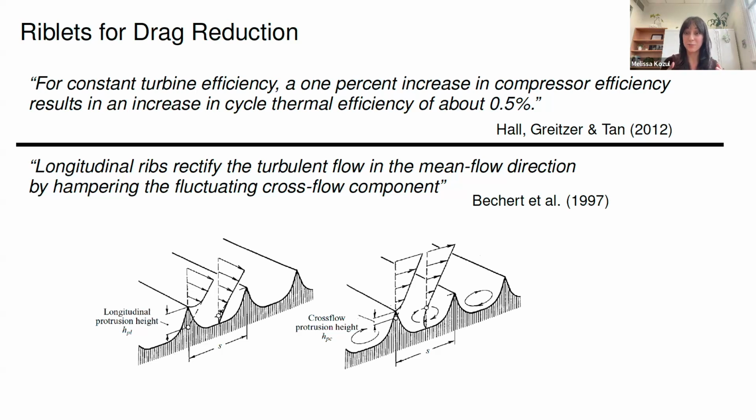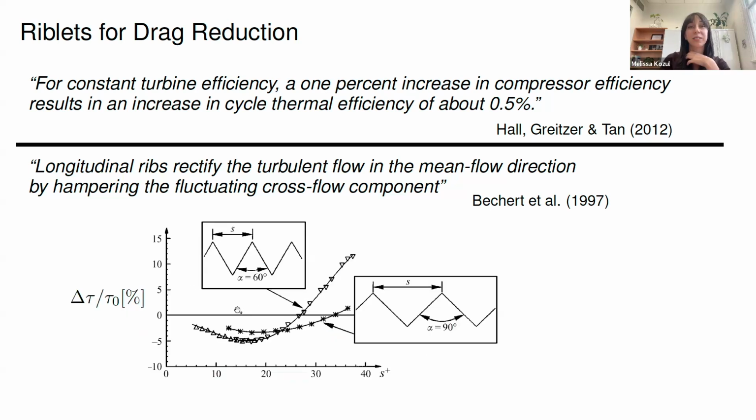that are microscopic in scale. Now, riblets only work in turbulent flows. That's when they reduce the drag. Because we have to have this fluctuating component, if it's a steady flow, they're not going to reduce drag. In fact, they will cause turbulence. Again, from these fundamental studies, we have S plus here, which is a viscous scale, so on the small scales of the flow, it's a type of spacing in the span. So now we're looking into the page at the shape of the riblet.